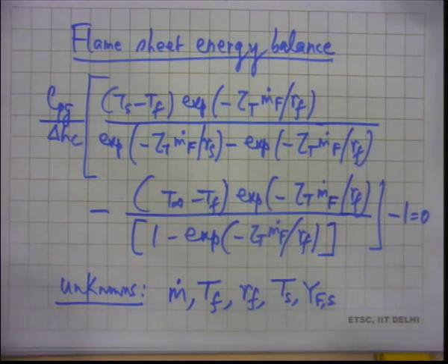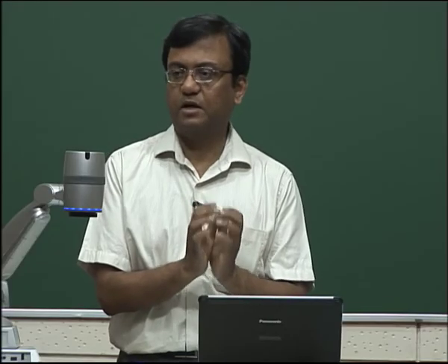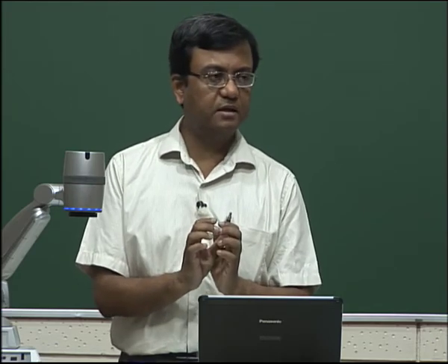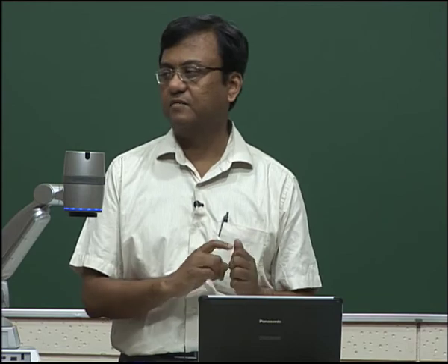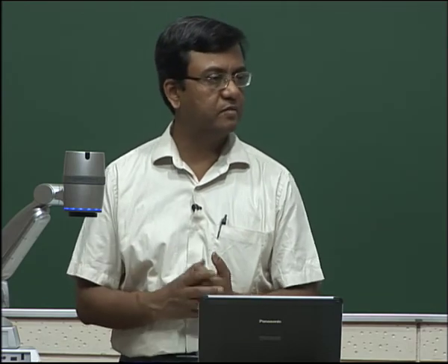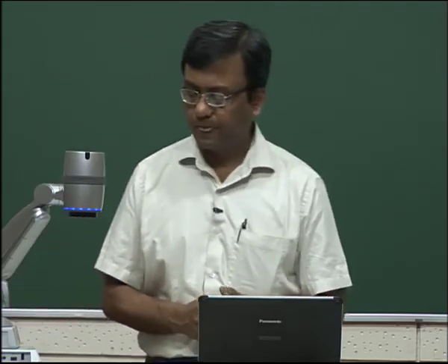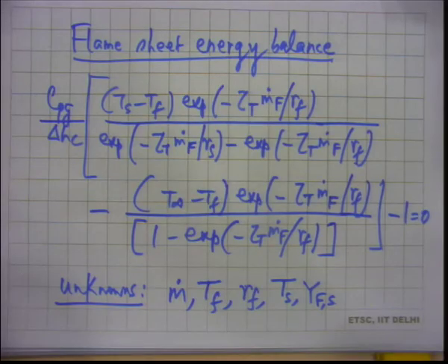This will find this function of RS at any point. So this is a quasi-steady model. This is like saying that the droplet has a radius of RS, and while it is at RS, it is establishing in the gas phase these temperature profile, fuel mass fraction profile and oxidizer mass fraction profile. So the time factor has not been brought in. Time factor will come again like the droplet evaporation problem. It will come towards the end.